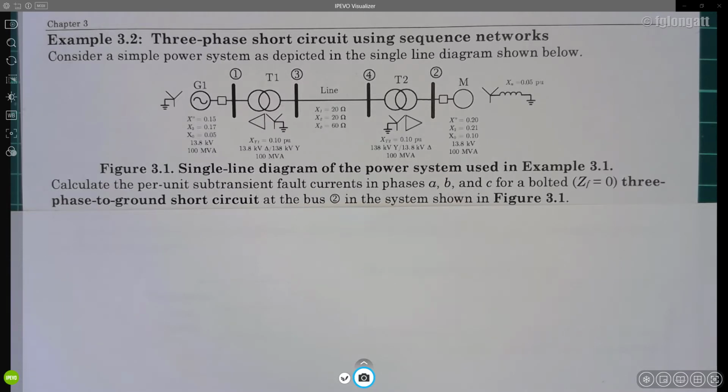Well, my idea here is that a lot of people don't realize that symmetrical components, this beautiful theory created by Charles Fortescue, can be applied to the power system, even if the power system is working on a symmetrical basis. Well, the job today is, let's start with this power system, but I will be running three-phase short circuit calculations, and in this case, I will be using the theory of symmetrical components. That is what is new here in this example, okay?